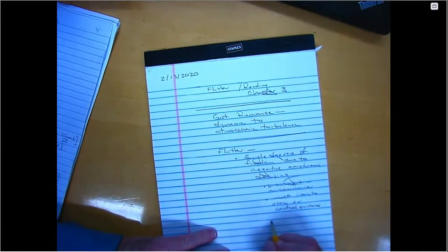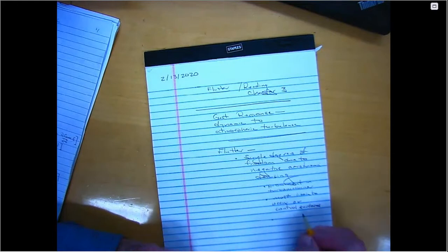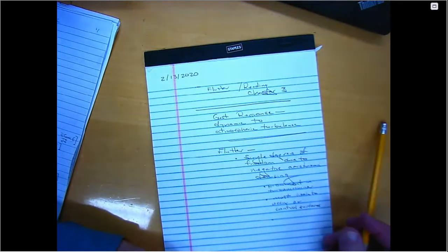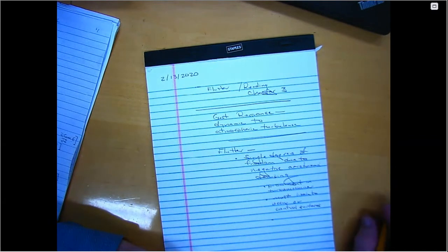And it's also most likely to occur in transonic flow. Actually, almost any kind of flutter is most likely to occur in transonic flow. So in a high-performance airplane, you find the dynamic pressure at which flutter occurs, and you can plot that versus Mach number. And usually it's in the range of Mach near 1 that you are most likely to encounter flutter.